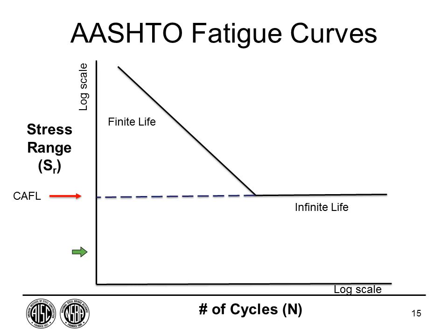That means the most compressed one there, -2 to -12, I think it was, if you calculate it, it's negative, but in reality, it's actually much higher than that at the weld toe. The only thing is that in AASHTO there is one provision that allows you to ignore fatigue if the compression dead load stresses exceed the stress range from the fatigue limit state load.